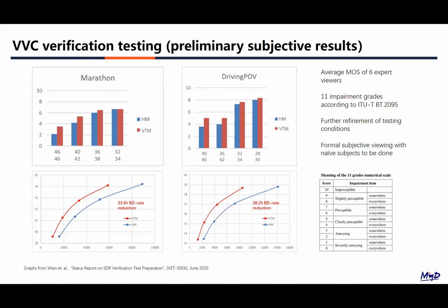So, video is not just about PSNR. It's actually more about subjective quality. So we have started doing verification testing for VVC using formal subjective testing protocols. Because of the pandemic, it's difficult at the moment to get naive subjects to conduct the tests. So we have gathered some expert viewers to compare the video between HEVC and VVC.